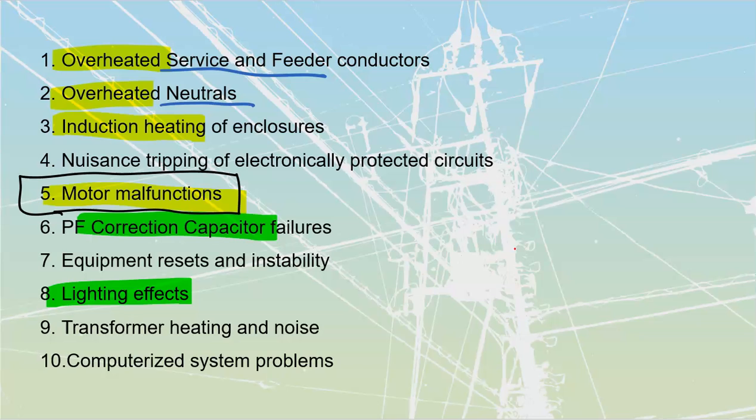That heating is going to be, once again, stray losses, right? Skin effect that we are going to see, so less room in the conductors. Hysteresis that we are going to have inside of the actual core and the casing. Eddy currents that we're going to have inside of there. Dielectric losses that we're going to have inside of the insulation around the conductors. All of those are going to go up. So we're going to see a lot more heat, and we're going to hear a lot more noise.